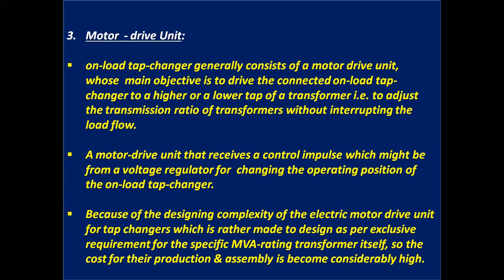Number three, motor drive unit. On-load tap changer generally consists of a motor drive unit whose main objective is to drive the connected on-load tap changer to a higher or lower tap of a transformer, that is, just to adjust the transmission ratio of transformers without interrupting the load flow.